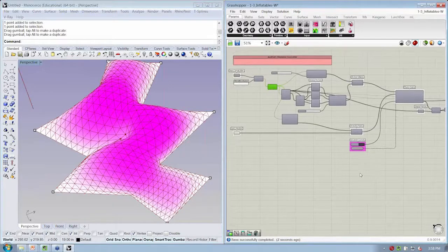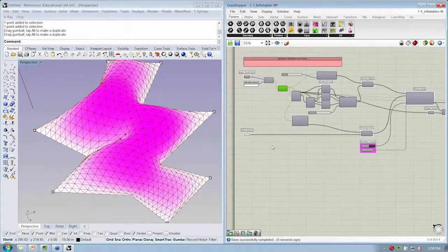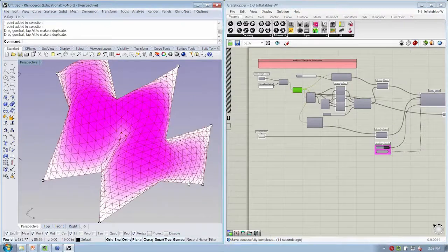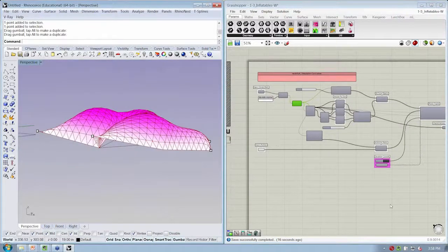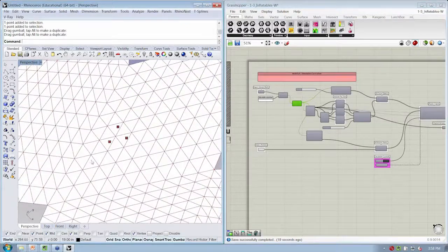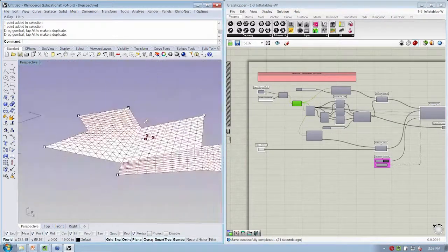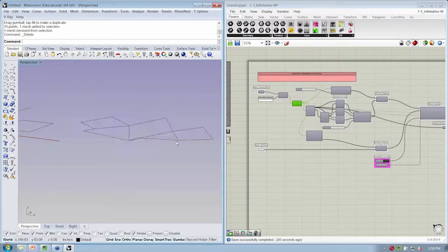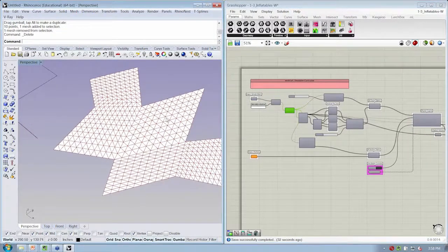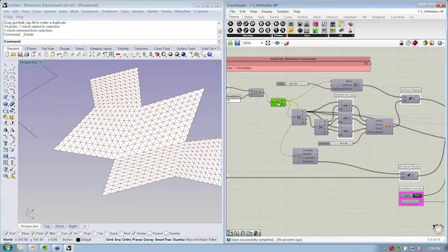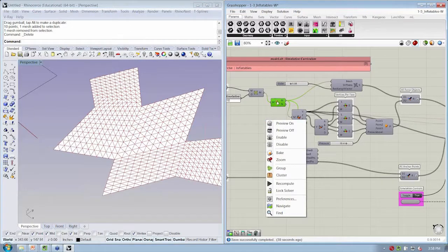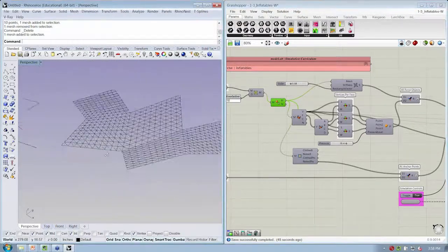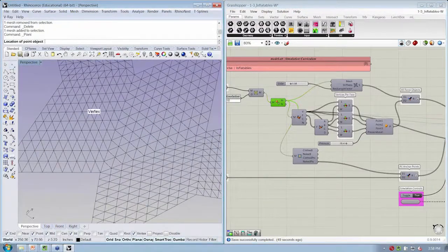All right, let's take a couple of questions now. The points that I just used for anchors, my process for specifying where they should be, because they have to be co-located to one of the vertices of the original mesh before it's simulated. So what I did was, if I go back to delete all those, this is just Grasshopper geometry right now, the subdivided mesh. So I'm going to bake it by right-clicking. This is the triangulated mesh. So now I have that mesh as a piece of geometry in Rhino. I can specify points wherever I want.